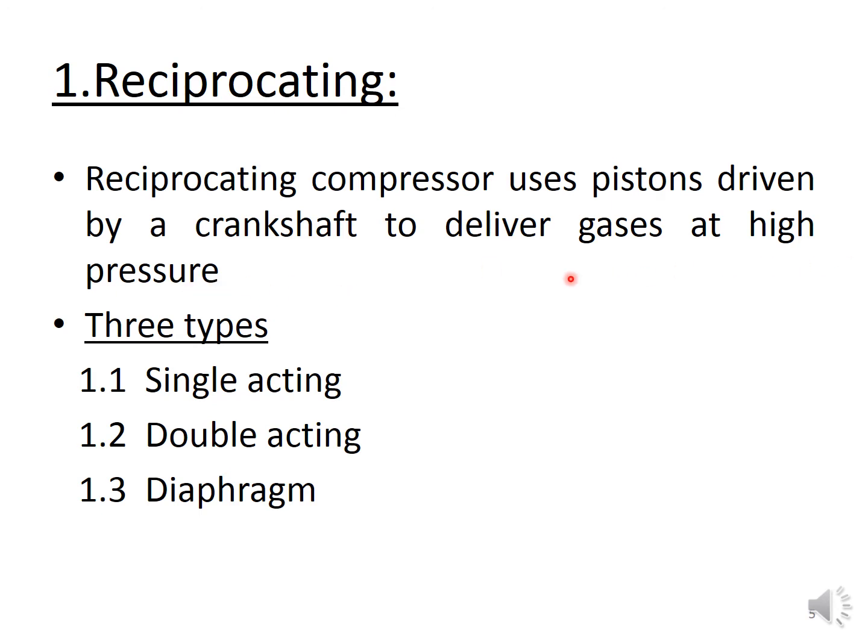Why do we use a compressor? We can use fans or blowers, but fans give us low pressure, blowers give us medium pressure, and in industries we need very high pressure for different processes. So if you need very high pressure, you use a compressor. For example, in your car tire, you fill the air. How much do you need? I think almost 2 to 3 bar, or in psi, 30 to 35 psi, right? If we need that much pressure, we use a compressor.